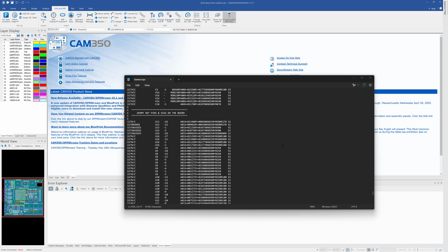Often they're just placeholders in a component where nothing is connected to a particular pin, or fiducials. Sometimes even tooling holes are defined by the designer in the CAD system and come across in the IPC Netlist, but we obviously don't care about those for comparison purposes.